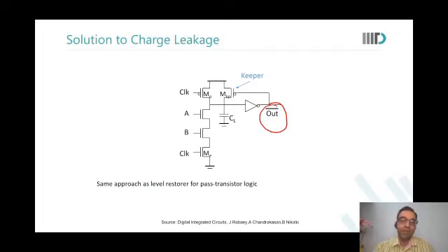At FS 125, highest voltage, because the PMOS is now slow, the PMOS keeper should still be able to compensate for the charge loss through the NMOSs, which are fast. Temperature is also high, so leakage is high. So why shouldn't I prefer FF 125? You will make the keeper also fast, and it will anyway be able to offer more current.